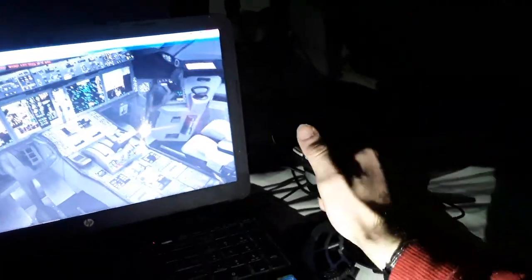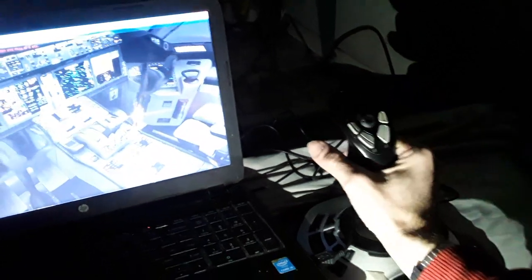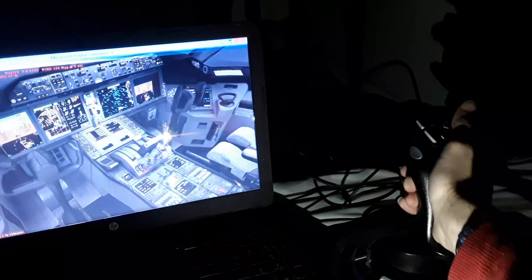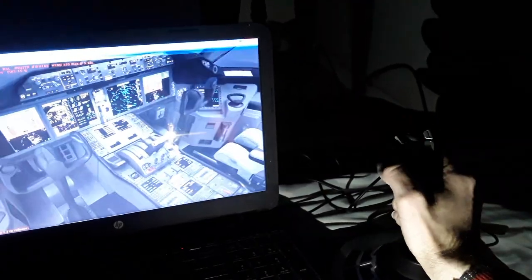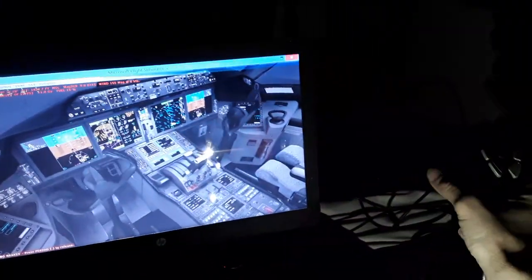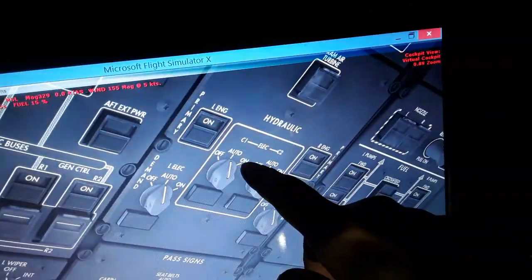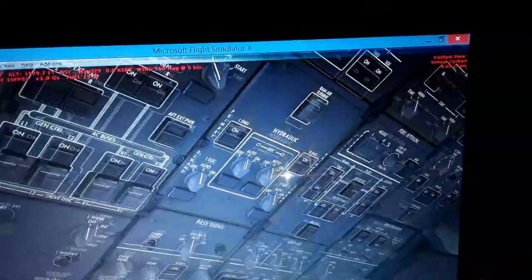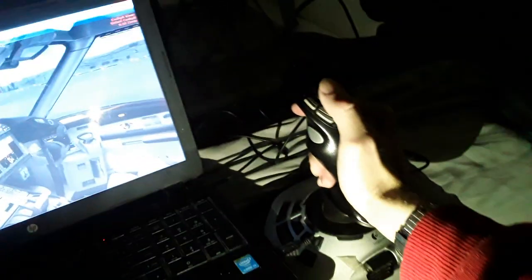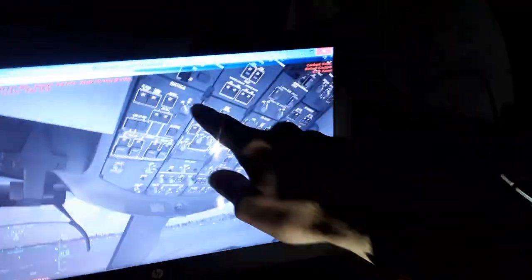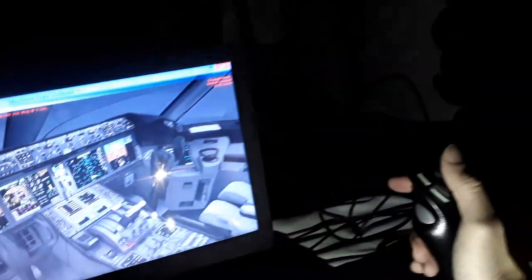When we move the flight controls, we have an electric flight control system, the fly-by-wire, that commands electrically the position of the flight controls. But you see the yoke, the control column, the control wheel, the rudder pedals all need hydraulic fluid, pressurized liquids, and this is pressurized with air from the engines, when the engines are working or we have the APU on.